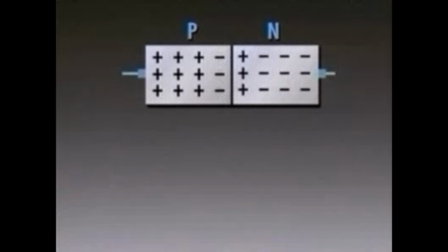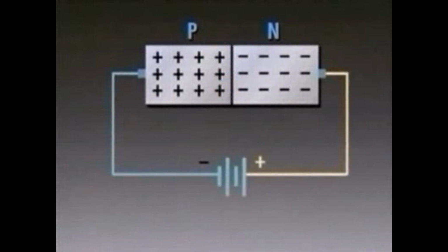When the junction is formed, a few of the charges diffuse across the junction in pairs. This depletes the number of free charges in the area. The buildup of charged ions creates an electrostatic field that acts as a barrier to flow. A p-n junction by itself forms a diode, which is a two-electrode device. Let's see why current flows in only one direction.